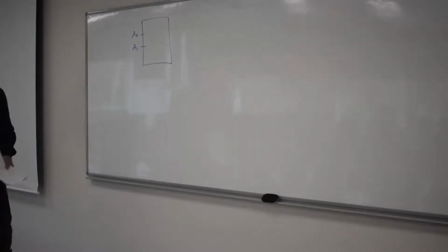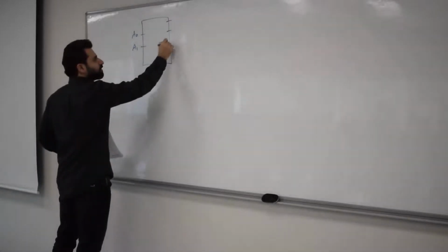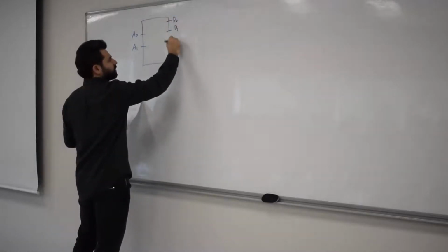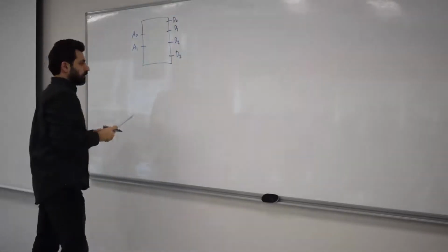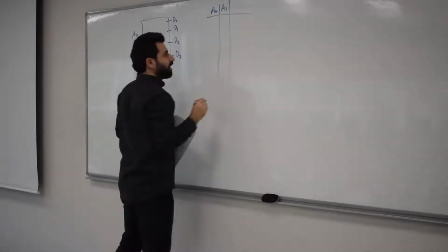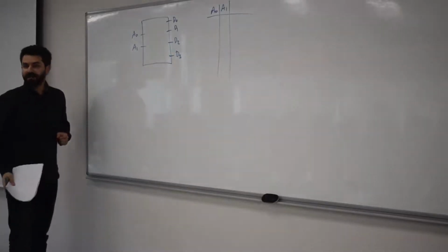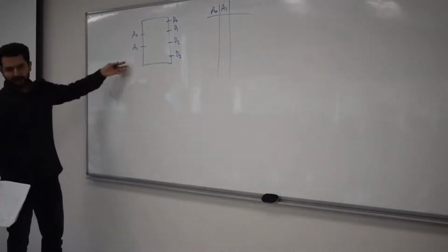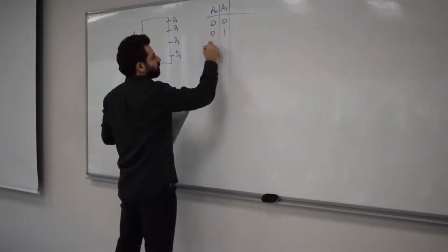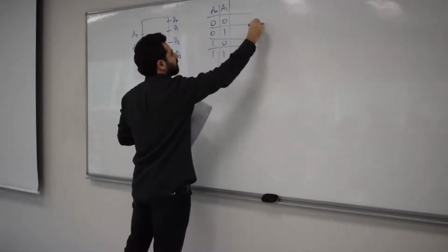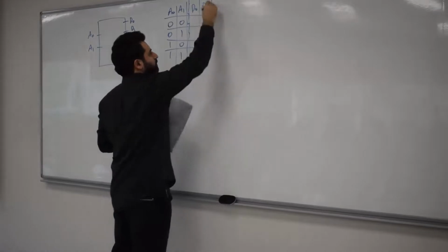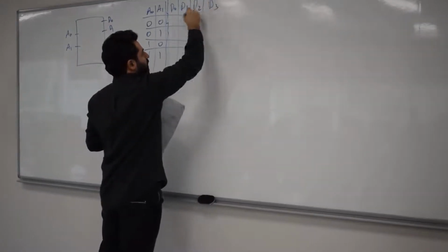Somebody gives you the code and wants you to figure out the outcome, and these outputs are going to be named D0, D1, D2, and D3. Here's the truth table. Now there is no possibility of having an invalid input because I'm going to span all the inputs: 0 0, 0 1, 1 0, 1 1. And these are my outputs, D0, D1, D2, D3.